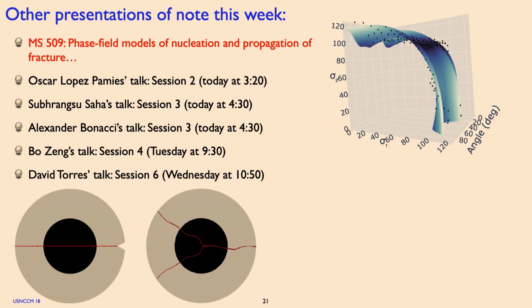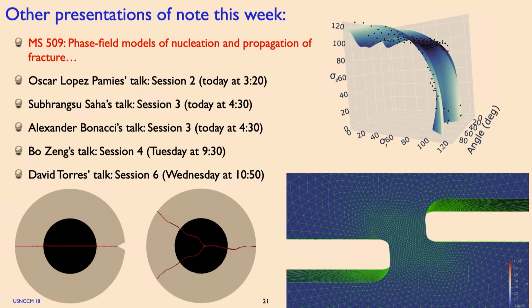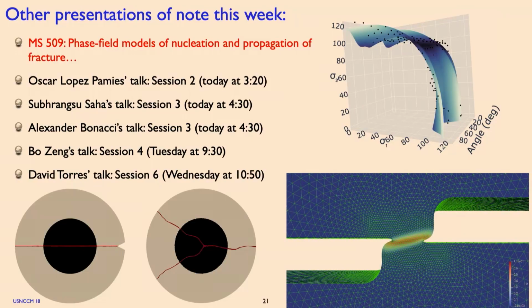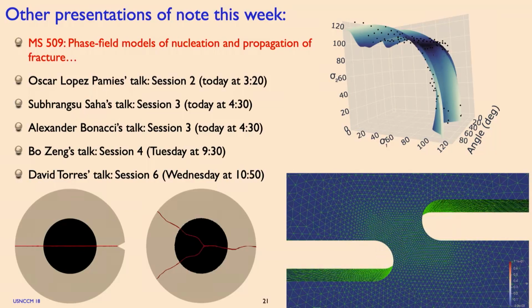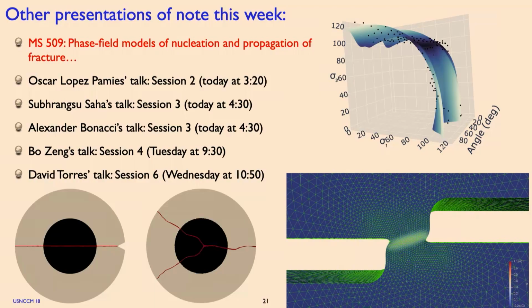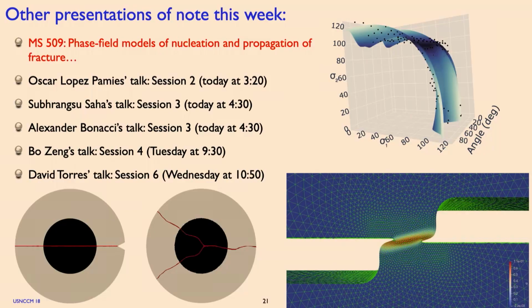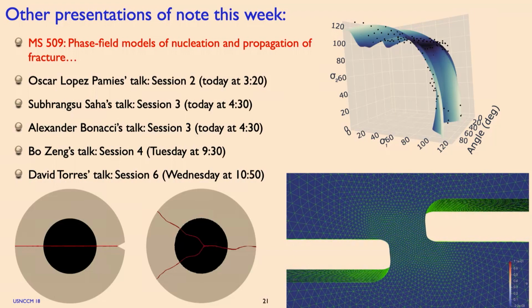Okay, I won't steal her thunder, but it probably won't surprise you that the explanation consists of both strength and energetics. Okay? The last thing I'll mention is that as we're pushing these models, building complete models, incorporating strength into the picture, we start to reach problems where the mesh deformations are significant, right? And so having to rely on adaptive remeshing and total remeshing in order to be able to investigate the models, particularly for ductile failure, where the shearing can be really significant, right?